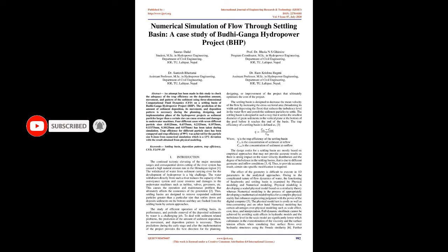Thus, settling basins are designed to remove suspended sediment particles greater than a particular size that settle down and deposit on the bottom, and they are flushed from the settling basin by certain approaches. The study of efficient operation of settling basin, its performance, and periodic removal of the deposited sediments by water is a challenging job. To deal with sediment-related problems, the prediction of the amount of sediment deposition, its movement, and deposition pattern is necessary. These predictions during the early stage and after the implementation of the project provide the best direction for the planning, designing, or improvement of the project that ultimately optimizes the cost of the project.